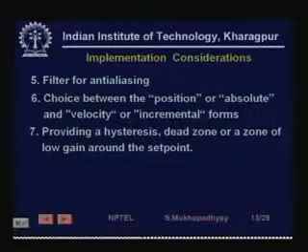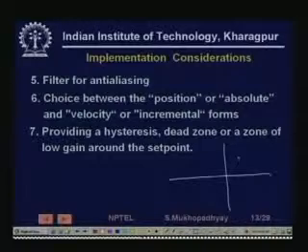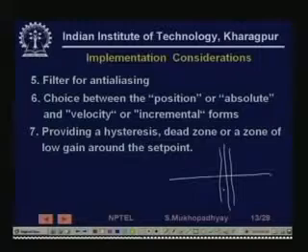Sometimes, typically as we have learnt in electronics also, we have seen comparators. So, if you have ideal comparators, then the output will keep on switching, right. So, therefore, we put either a hysteresis or a small dead zone around the 0 point. So, we say that if the error is a little bit here within this zone, then I am going to keep my control output as before. So, you put a hysteresis, let me draw it clearly.